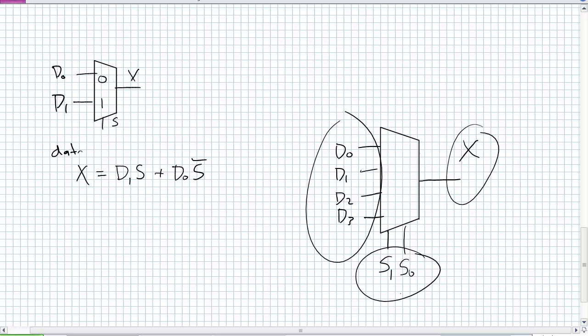That's kind of the data flow version of VHDL. I know I haven't written in VHDL syntax. You should be able to do that. Now, obviously I'm going to have you do the structural using 3 2-to-1 multiplexers to create a 4-to-1 multiplexer. There's another way I could describe the behavior of that particular 2-to-1 multiplexer, and that's what's known as a behavioral description within VHDL. I can use that 2-to-1 multiplexer in either data flow mode or a behavioral description as a structural component.